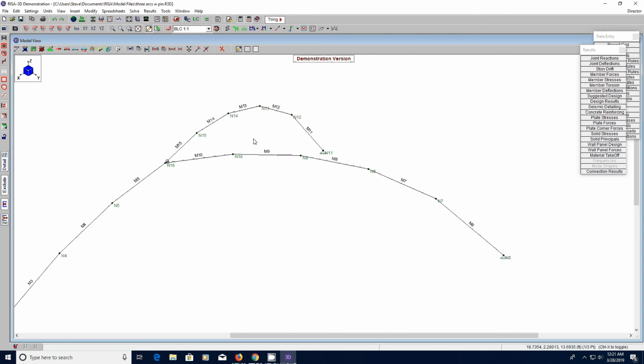We don't have that in the two-dimensional version because it's flat and it's considered to be stable in and out of the page. Well, we don't have that in the three-dimensional version. So what I'm going to do is add an additional restraint where this can no longer spin about this point. It's still a pin in terms of bending moment, but it just can't spin about that point.